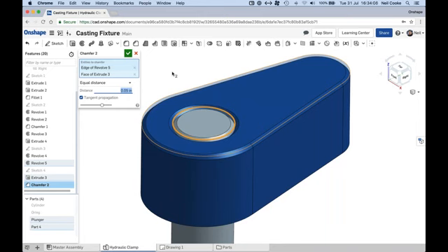So yeah, someone's mentioning there, parts on Onshape are equivalent to bodies in SolidWorks. From a basic standpoint, yes, but the difference is that in SolidWorks, if you wanted to use those bodies in different assemblies, for example, you would have to save them out as bodies individually, and then have an extra file which controls those parts. These are parts in their own right. So this part 4 can be used in 10,000 different assemblies, but still be generated from this part studio. So that's probably one of the main differences. And the fact that they can all have different materials, properties, and whatever else, you can do that as well.